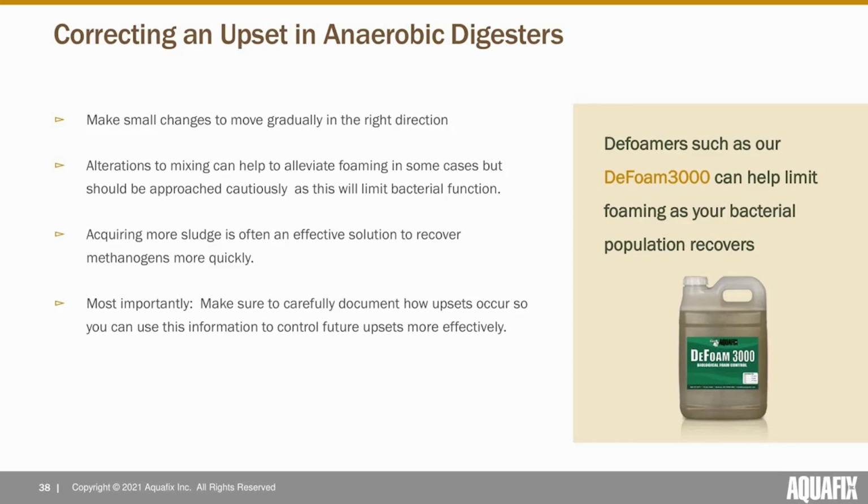Alterations to mixing can help alleviate stress, and defoamers can be really helpful as short-term solutions as well for foaming and that sort of thing in an anaerobic digester, because as you're trying to stabilize your digester, foam is likely to crop up over and over again. Having a little on site can give you a lot more security, so you don't have to deal with a major foaming event. This is not an efficient solution for the long term, but this sort of thing is a great helper for recovering your process without having major foaming taking place. Another note that's very important to think about: if you have an upset, make sure to remember what happened last time, because there's a decent chance something similar will happen in the future.